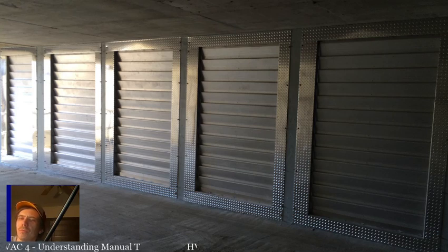The old trick of using a lighter to test the draft, where you put the lighter real close to the draft hood and see that it gets sucked up into the flue, is not going to work when it first starts up. You've got to let that flue get warm for a couple minutes, and then you should be getting a good draft up the flue.